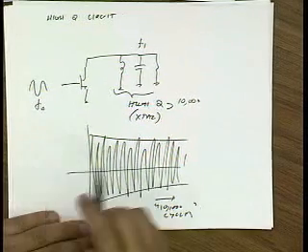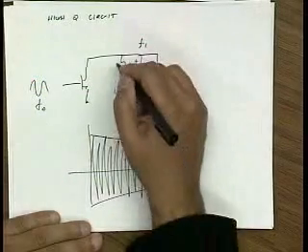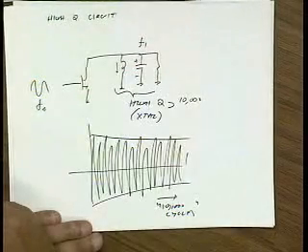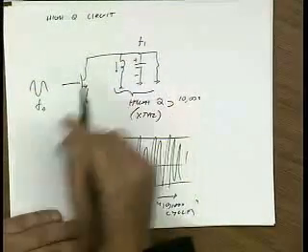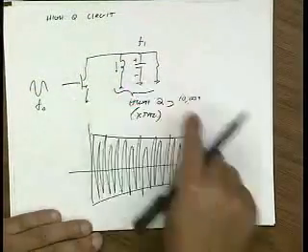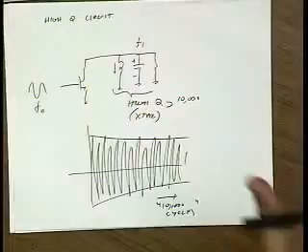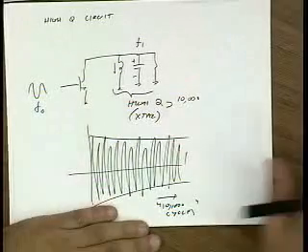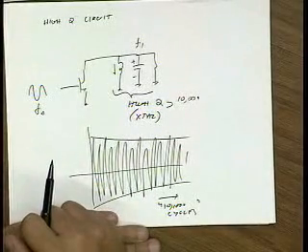On the other hand, if I could find the final charge on this capacitor and current in this inductor, and also the same inside here, all the voltages across the capacitors in here, that result in periodic steady state, I could just apply those voltages and boom, the circuit would be in periodic steady state. It wouldn't ring at all. So that's the idea behind PSS.